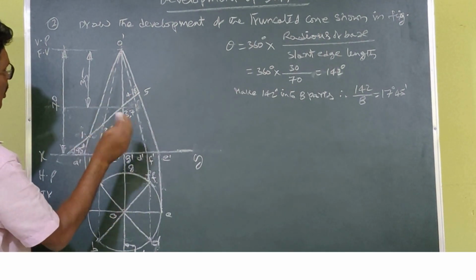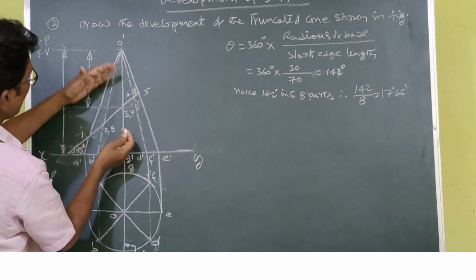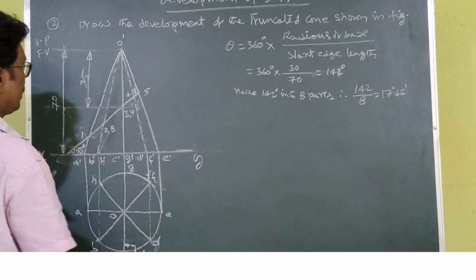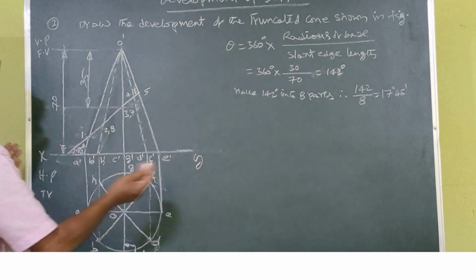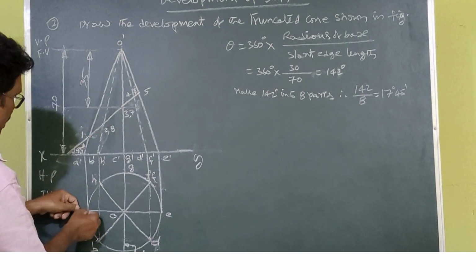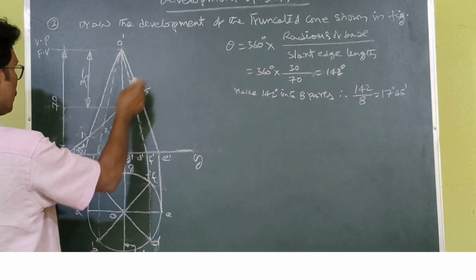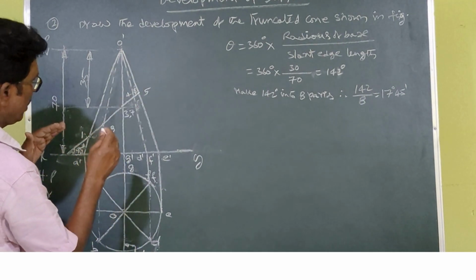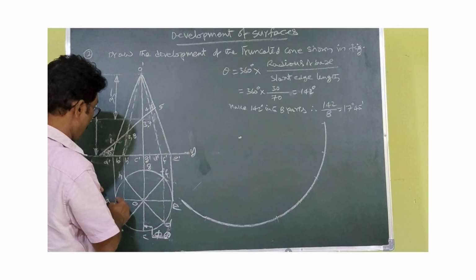Now we can develop the bottom surface area of this plane, or the top surface area, whatever we want. First we have to develop the entire cone. If it is opened, let us assume at A, we open this cone. The cutting plane is going on like this, cutting it like this. How does the surface look? If you want to expand, open at A.